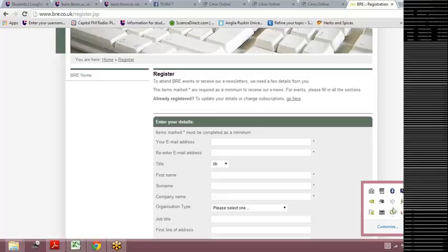Yeah, you could consider covering off the area. When you're working on the new site, you can consider covering it off so the debris doesn't spread. What we did for our project was we completed the entire new building. We had to make an extension to the old building. So we completed the entire portion of the new building first, and then during the holidays and so on, that's when we started working on the old building.